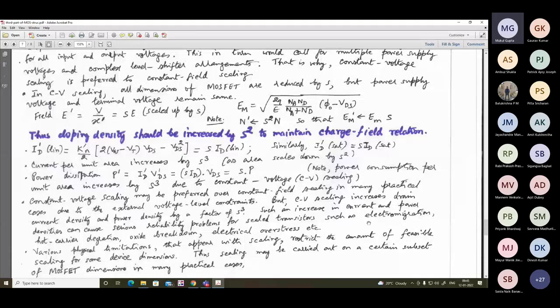So what will happen with the increase of excessive current density? The metal ions tend to migrate towards the direction of the current, and if it does so, it will lead to a gradual reduction in the width of the metal wires, over a very restricted region, but eventually it may lead to a simple discontinuity of the metal wire. That means electromigration, the migration of metal ions in the direction of the current, is harmful. When the current density increases excessively over a segment of the interconnections, eventually at some fixed locations the wires can get snapped and become discontinuous.